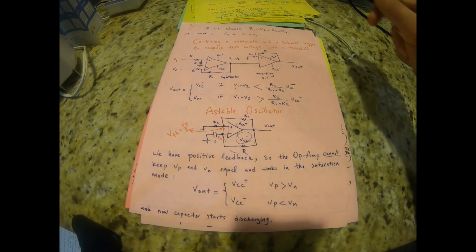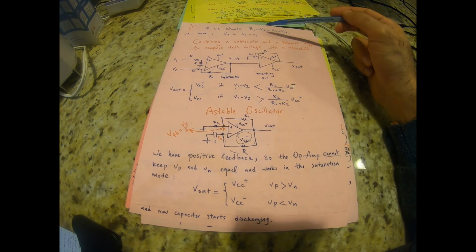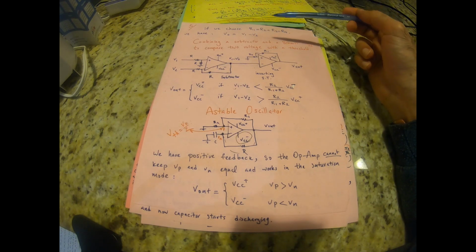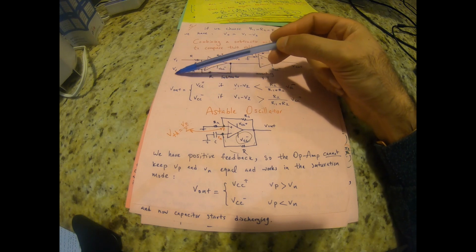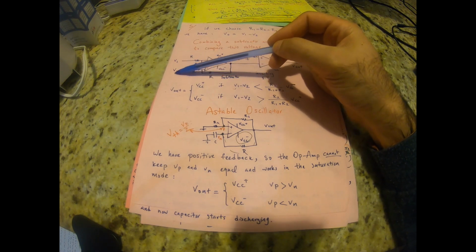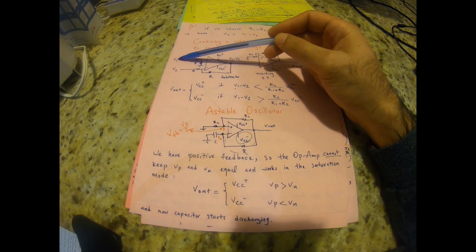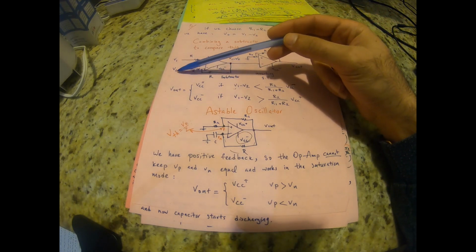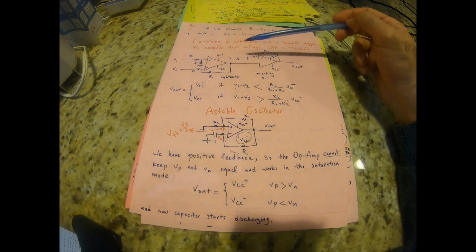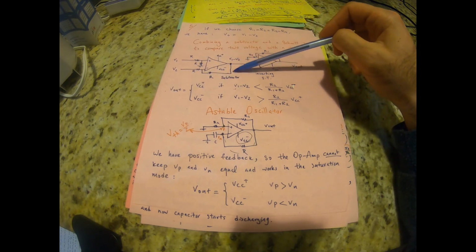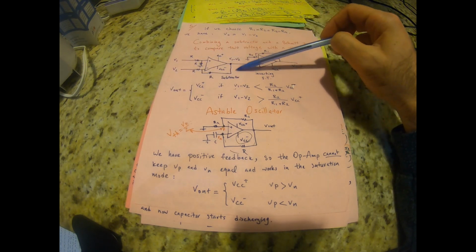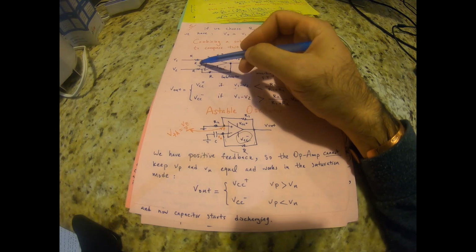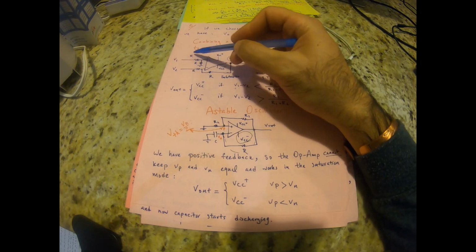So if we choose all the resistors to be the same, V out is going to be equal to V1 minus V2. If we want to compare two different voltages, two different signals, and see if one of them is bigger than the other one, we want to have a positive voltage if V1 is bigger than V2. If V1 is smaller than V2, we want to have a negative voltage. Then we can just first have a subtractor circuit that provides us with V1 minus V2. How can we achieve that? By having all the same values for all the resistors.